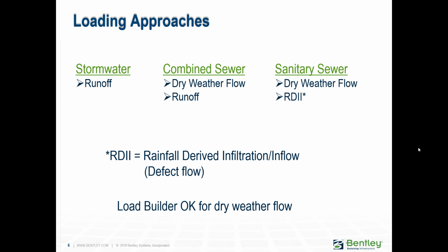With LoadBuilder we can use the GIS input to load all the sanitary sewers from water meters, and then we can also use LoadBuilder to load dry weather flow from areas with density and census numbers.